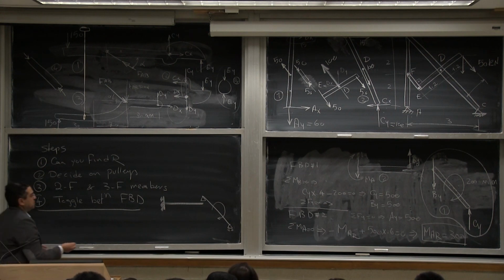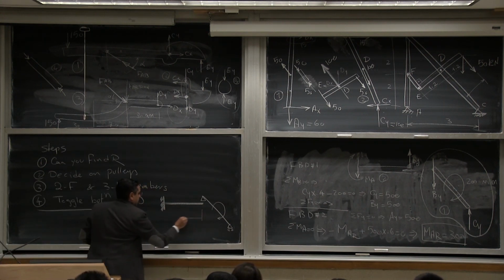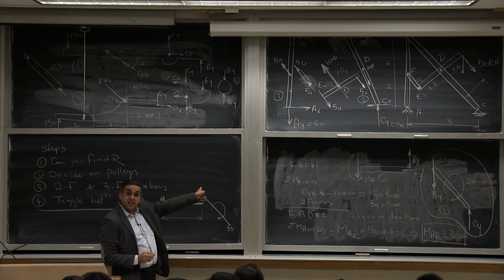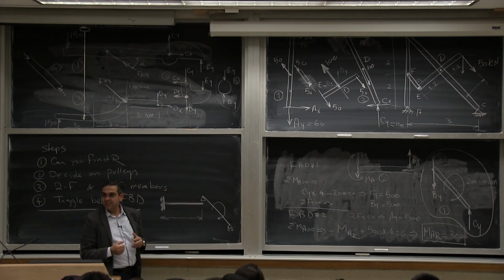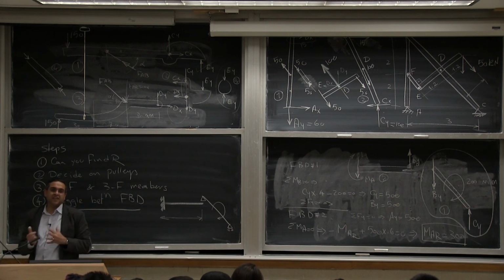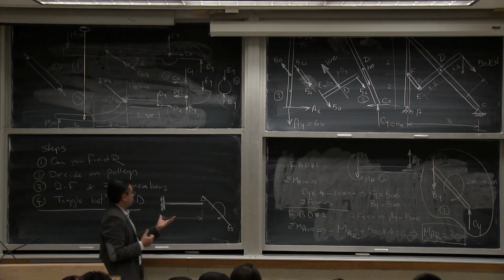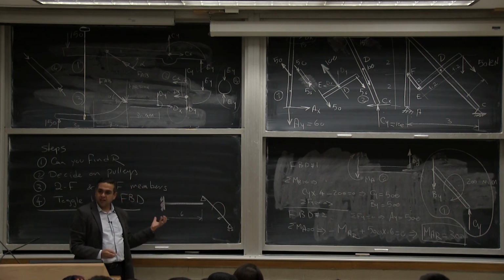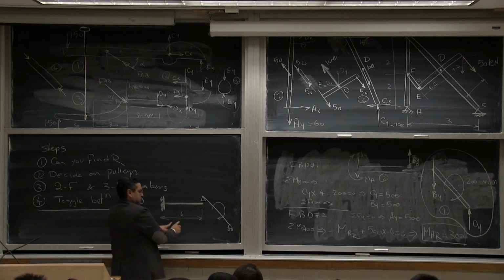And the fact that we made this way too long got us to handle a 200 Newton meter with a reaction of 300 and a force of 500. So our dimensions were not that good. If I reduce the 0.6 here, then I will need a smaller reaction, because we said it's 500 multiplied by 0.6, that's 300.